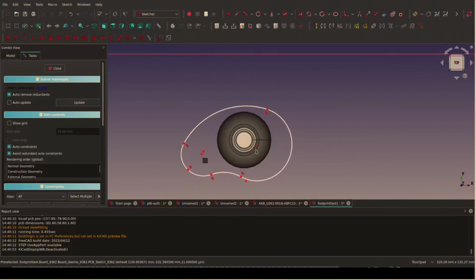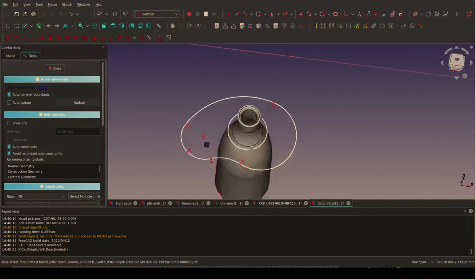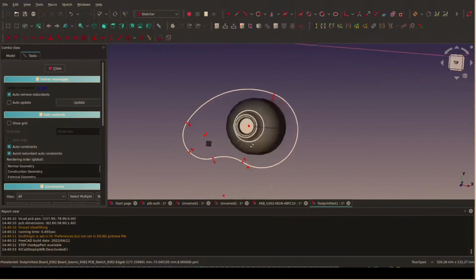If you have a bunch of parts on it, you can also see like, okay, we cannot move things around there because then there won't be enough space for the parts and things like that. So now we're adding a cutout for the bottle. Now this is a 2D view, but we can actually rotate it in 3D and use that to adjust just that to make it fit exactly that spot on the bottle.